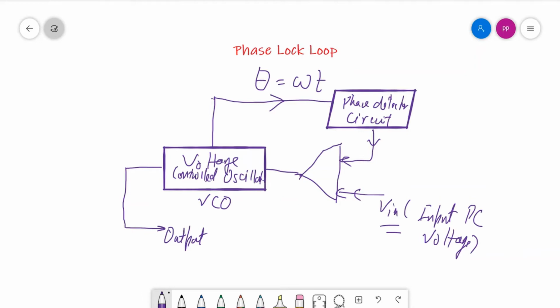The VCO is basically converting the voltage into frequency. So a VCO is a high frequency oscillator of LC circuit. It has many capacitors in combination with inductor or inductors to produce a high frequency oscillatory circuit. Here, one of the capacitors of the VCO is replaced by a varactor diode.